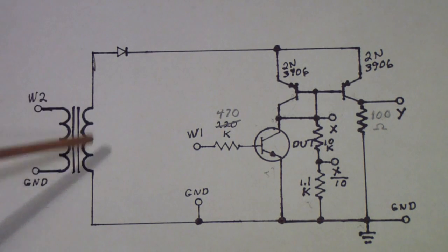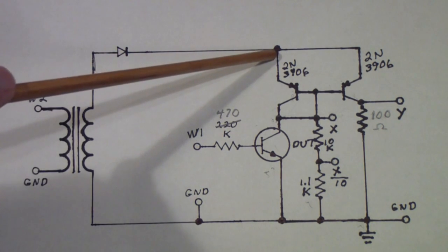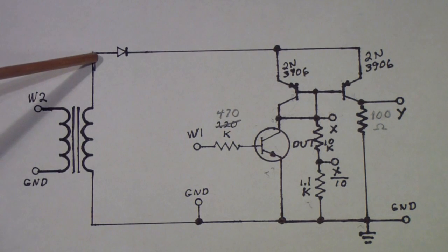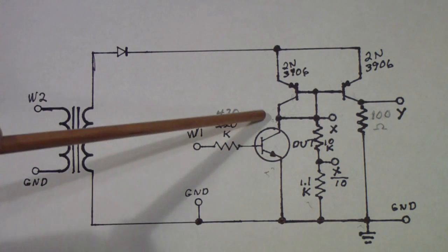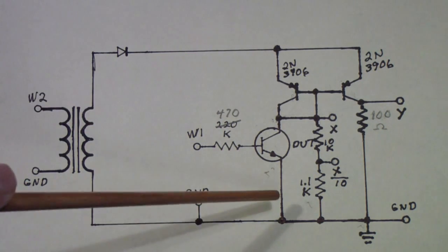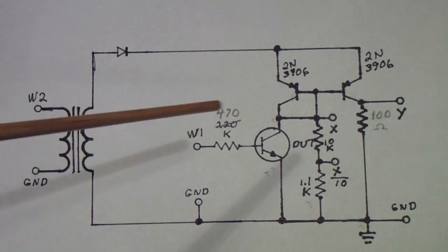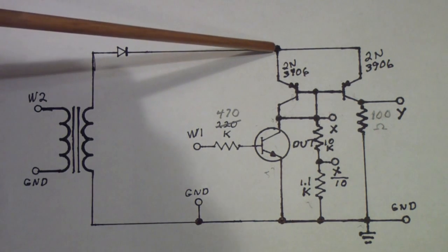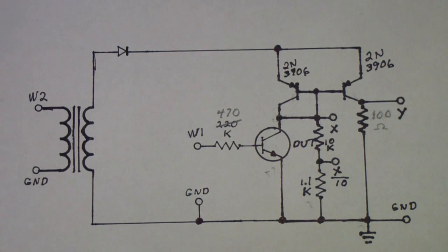Previously, we had realized that we did not get enough collector voltage out of the Analog Discovery, so we used a transformer to give us some step up so that we could get this transistor up into the 15 or so volt range that it's designed to operate in. This transistor will operate up to 40 volts, but normally it operates off of a VCC range of 12 to 15 volts. So we wanted to be able to get to at least 15 volts here. And we were able to achieve that with a transformer.